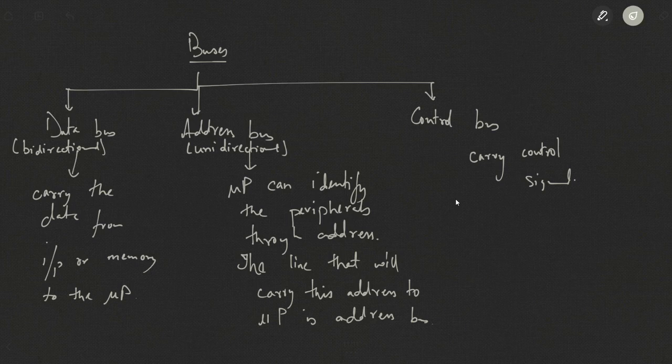The addresses of these peripherals will be 16-bit digits rather than 8-bit digits. So this thing needs to be distinguished in an 8085. The data processed by the 8085 is only 8-bit, so it's only an 8-bit microprocessor. We will not call it a 16-bit microprocessor.